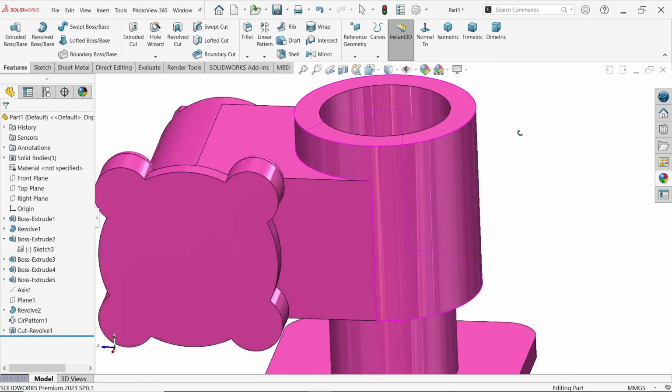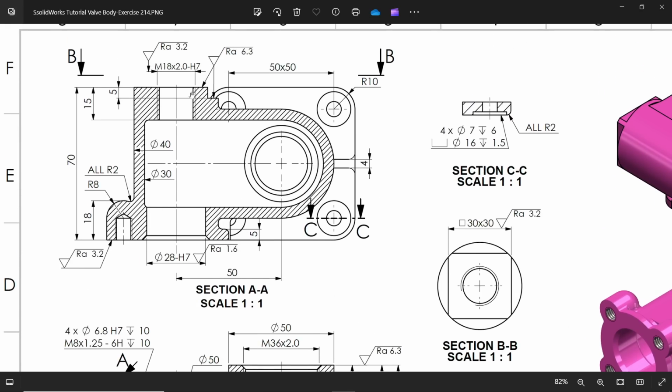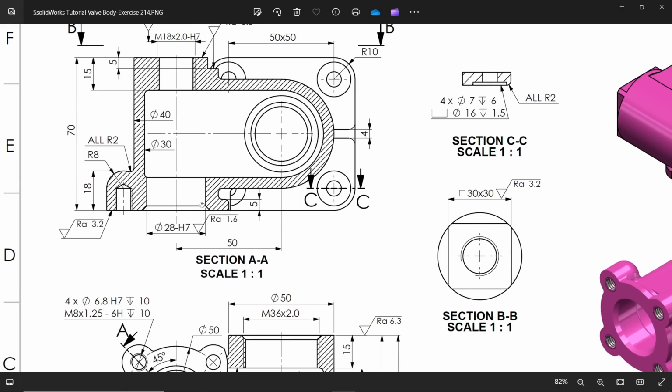here we cut. Let's come up. Now here let's cut this. Now here we have thread, so we will cut later. First we will cut this 30 millimeter, and this is going to be 50 millimeter according to drawing. Okay. So this is going to be balance diameter 28.